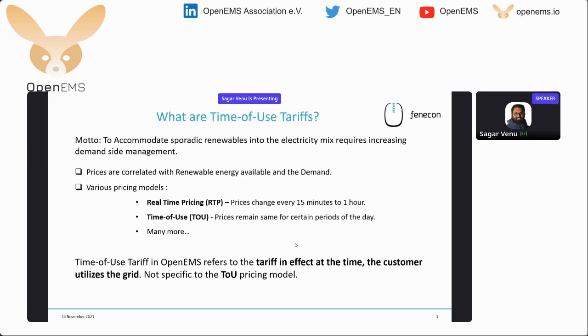So time-of-use tariffs, which are generally known as dynamic prices, are a demand response program. Unlike offering flat electricity prices to the consumer, the utilities offer dynamic prices which reflect the renewable energy available and peak load demand. Before, it was not possible for the providers to give these price signals. With the advent of technology and smart metering, it is quite easy for the providers to send these price signals way in advance to the customer so that he is well prepared for these prices.